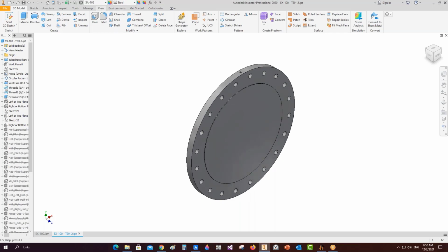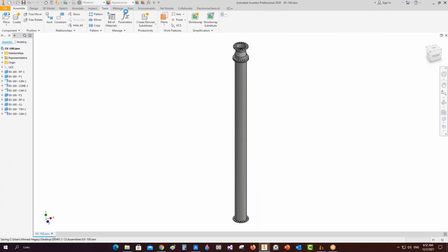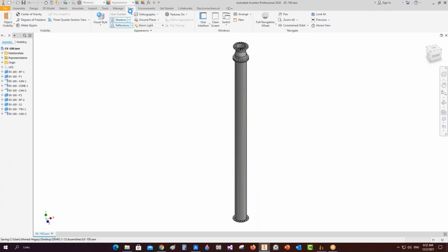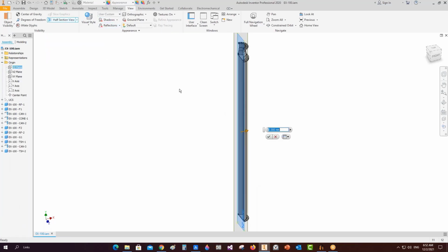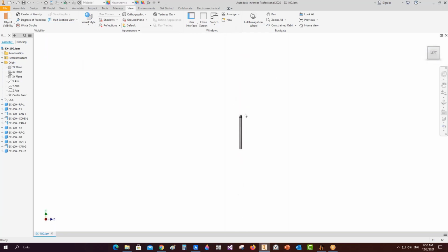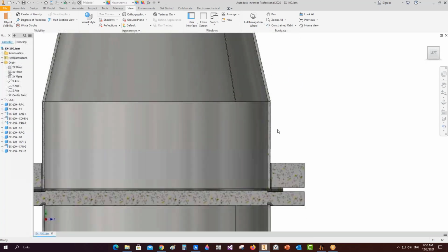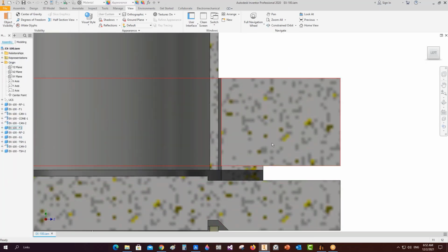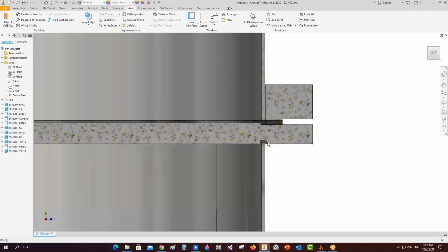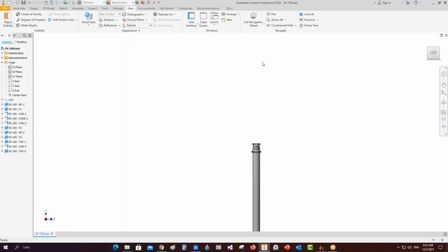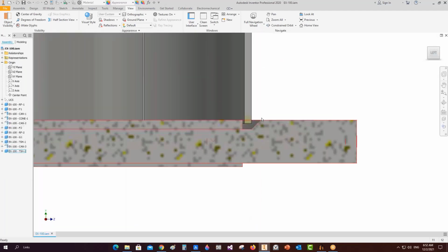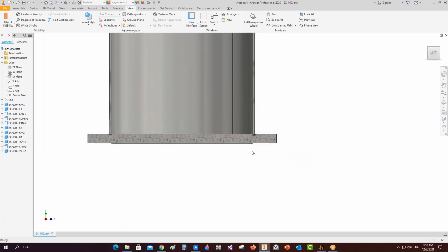And if we take a section view on the model to see the arrangement of elements, on the assembly here, we will open the view tab, and from here, let's select a half section, and let's make a section here and take a look at the elements. So you can see that's the connection here, the body flange, the raised face gasket, the first tube sheet, and here you can see that the clearance is 3 millimeters. If we come down here, that's the second tube sheet and clearance.